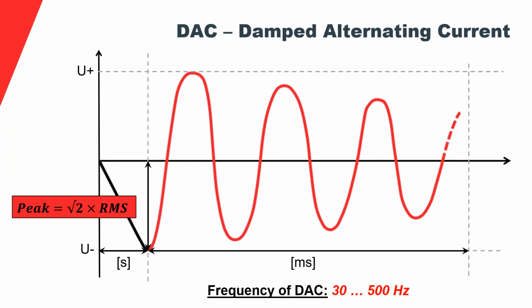The next step will be 10 hertz, because for the very long cables, they have to go down to 10 hertz. Multiple series and paralleled resonance test sets can only charge these cables at 10 hertz. So that is the latest development there. And as you can see, it's over in 200 milliseconds. You have an oscillating damped wave shape. You're charging the cable, you're causing the resonance, you have a power frequency related effect there.